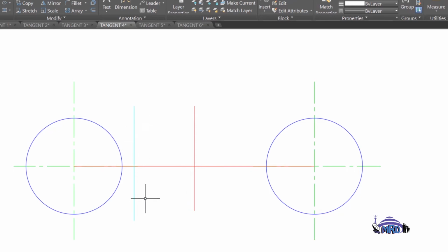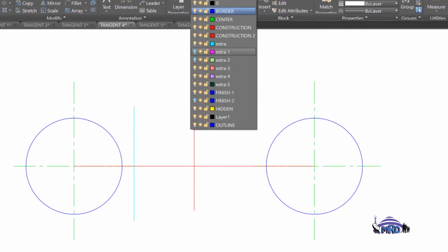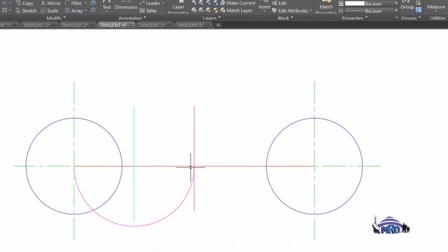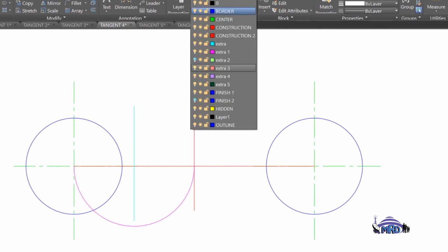So this second bisector is the bisector that we want to use, and we're using the center point that we have formed here to now draw a semicircle at the bottom. So this, as I'm representing now, would be that semicircle. So we have this semicircle in place, and we now want to locate the normal for the tangent. You're always locating the normal, and remember that the normal is a radius line. So in this case, the normal would be from the center of the circle to the point of intersection between this semicircle and the main circle that we started out with. I'll just show you that normal in position.